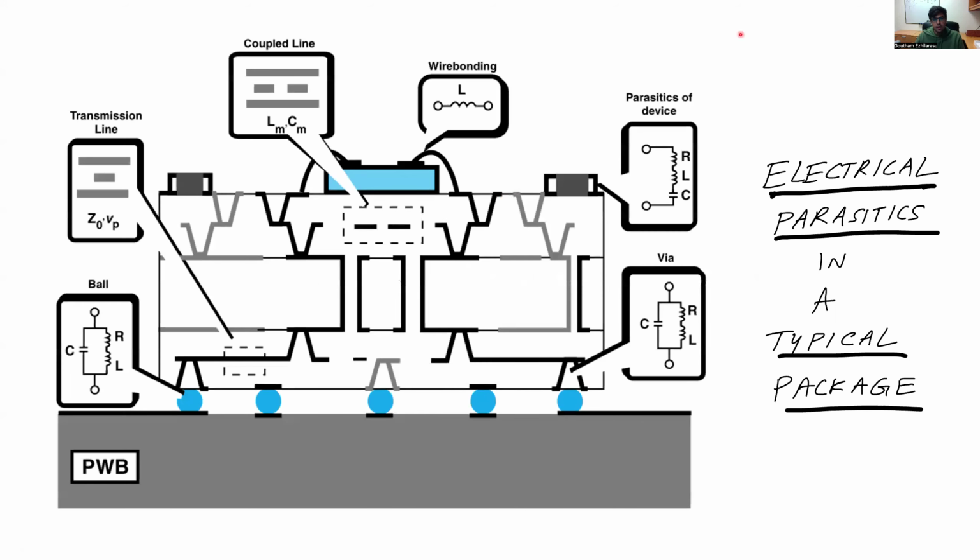As we had talked about earlier, what is signal integrity? Signal integrity basically has to do with how we can reliably send a signal from a transmitter all the way to a receiver on the other side, which could be between two chips or between two different packages. It doesn't really matter. The signal sent from the transmitter is usually a digital signal. And as we will see, a digital signal, depending on its rise time, can have a very broadband frequency spectrum. So the question is, how can we send the signal at the transmitter side and then reliably recover it at the receiver side?